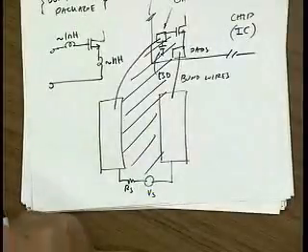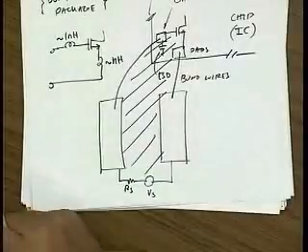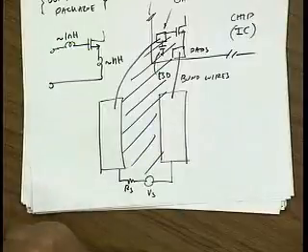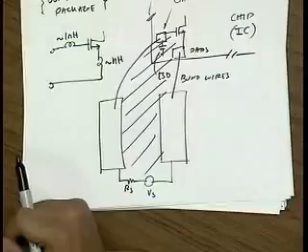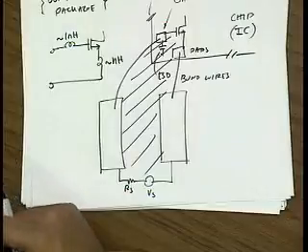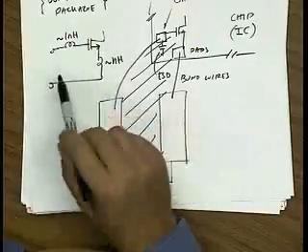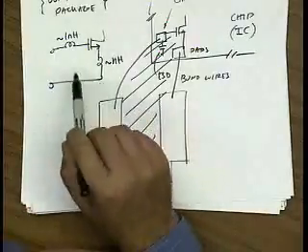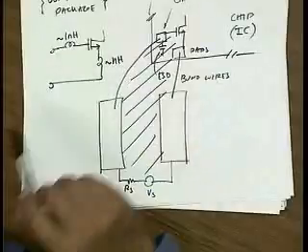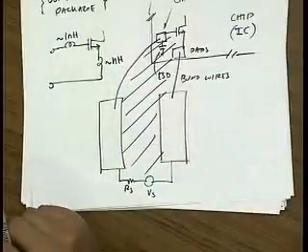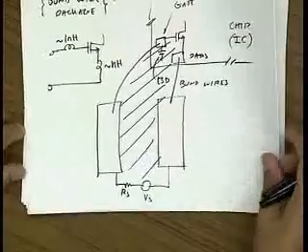Now, there's lots of packaging technology to try to reduce these inductors. But at the end of the day, you're going to end up with, at best, hundreds of picohenries up to tens of nanohenries if you're in a really large package. Okay? So somebody clever realized that this is actually a good thing. I can absorb these inductors into my circuit and make my circuit better. So let's see how that's done.